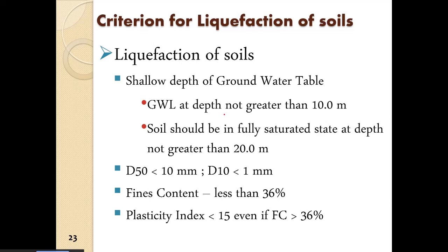Some brief criteria, some important thumb rules, were given by the various standards, and they can be summarized to a few points. One is of course the shallow depth of groundwater table, obviously. The groundwater table has to be at a shallow depth.